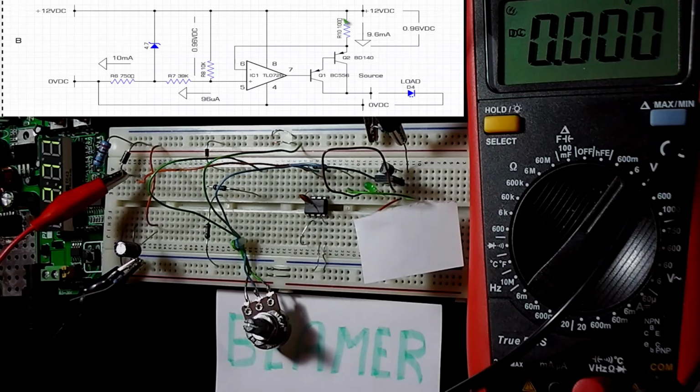So I have a solution for that. It's pretty obvious, and that is to whack another diode in the supply, therefore producing a 1.5 volt drop and placing the op-amp 1.5 volts DC above the compliance voltage, and that's what I do now.